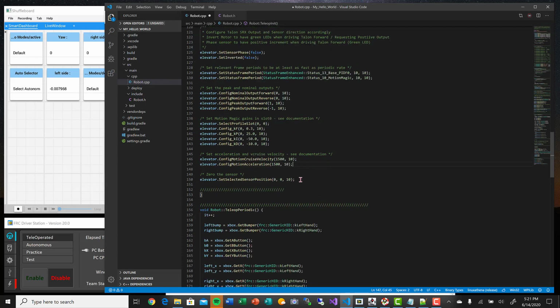For now, when we start up, when we do the init, we're going to reset the position sensor count to 0. In an elevator application, you'd do something more sophisticated and make sure the machine's at the bottom. There's actually a way, when it hits the limit switch, to do this automatically. For now, we're just going to start with a 0. But this is a one-time configuration when you go into the teleop mode. And you'll see the cool stuff next.